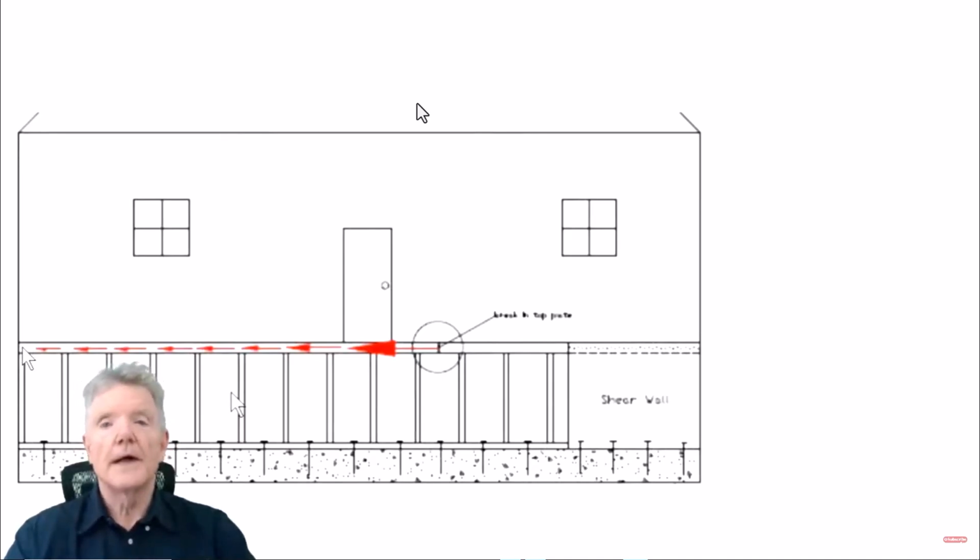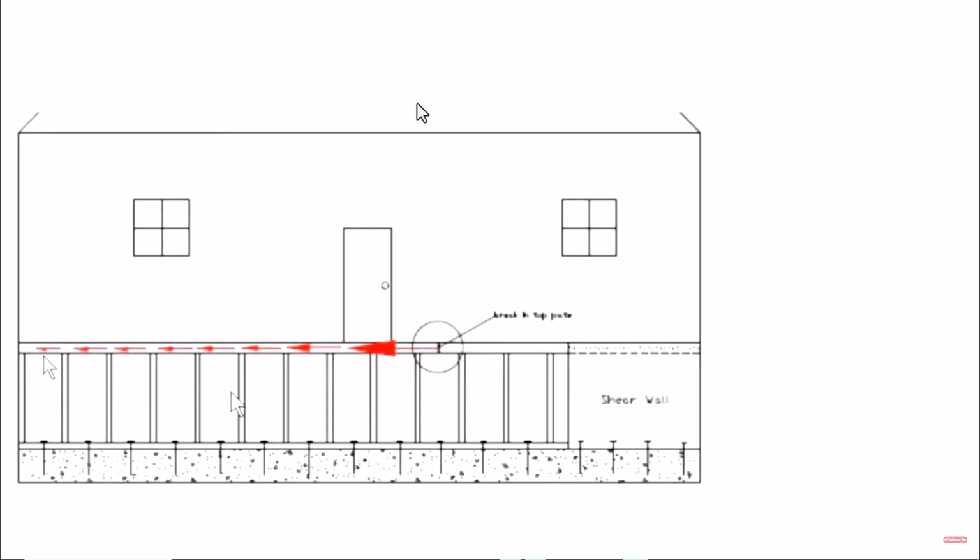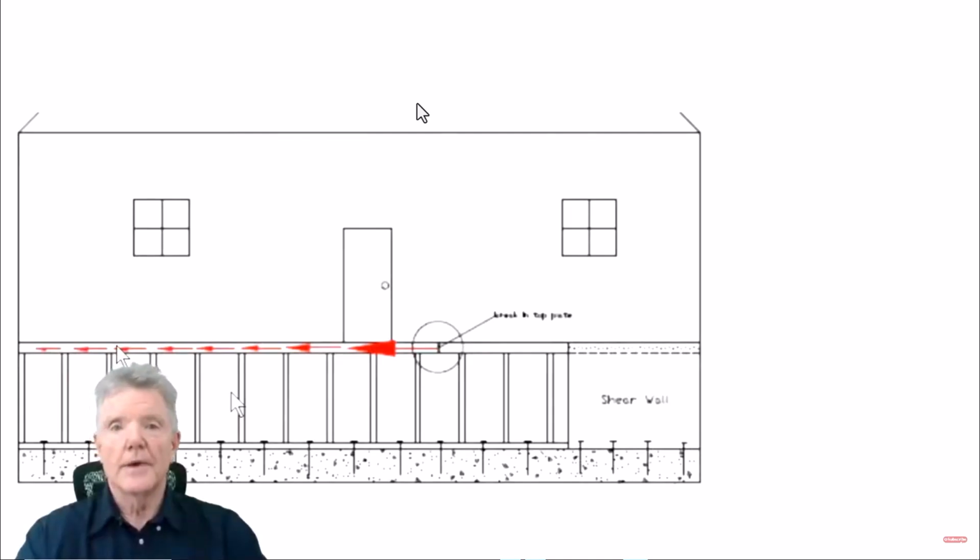So what you will find is a board that's 10 feet long, and then another one that's 12 feet long, and then another one that's, say, 25 feet long. And so all of these create breaks where they're butted up to each other. So here's an example right here. This is a break in the top plate. So that's the break. So there's a board this way. This is one length of board, and then there's the other board that goes this way. And we'll see right now why that is a problem.